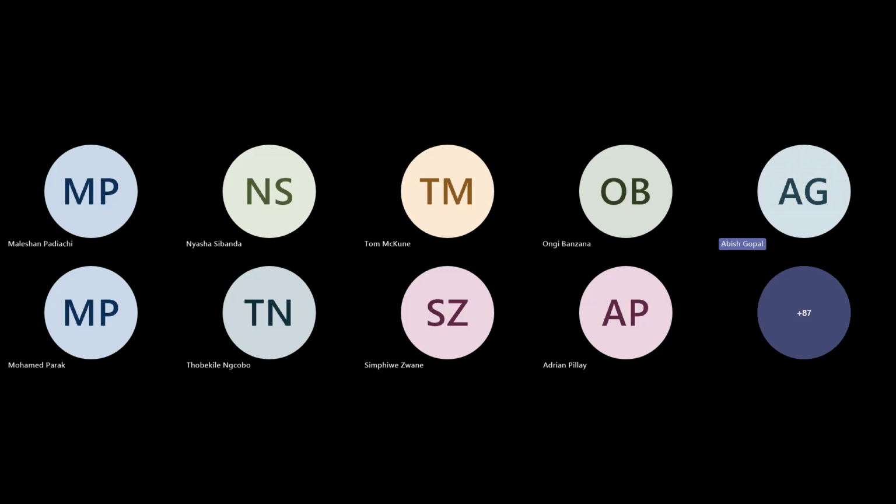However, a full EIA process was undertaken, and in terms of the triggers, the major one would be we are working in an estuary. So an estuarine specialist was appointed, and in addition to that, a heritage specialist was also appointed because the bridge is over 60 years old. So those were the triggers.